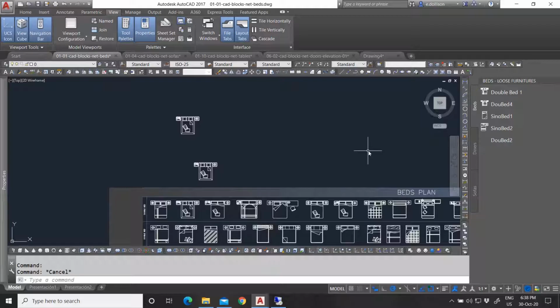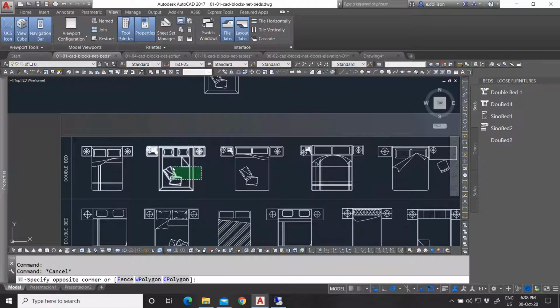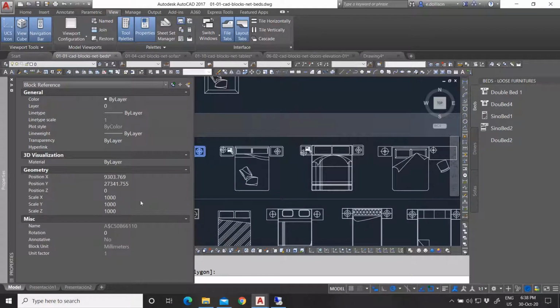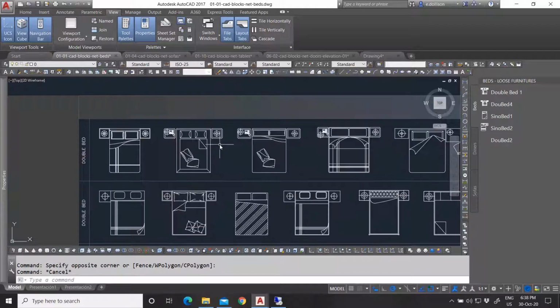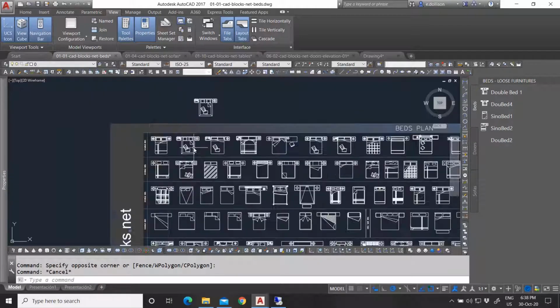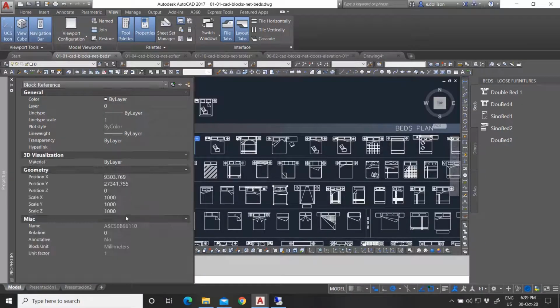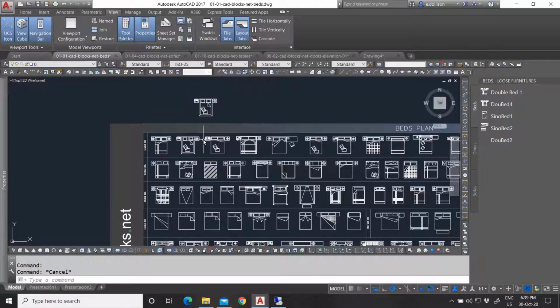It is kind of tedious, but take the time to do this correctly. Don't get caught up in what I just fell for, that this block was already resized to 1000. So that is a tip. Make sure all your blocks are the same size for real and not just scaled by hand, which is actually very easy to fall for.